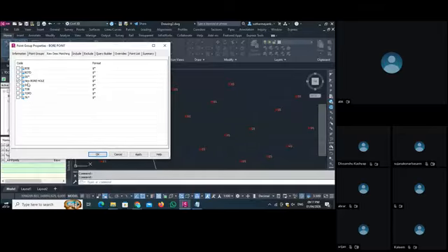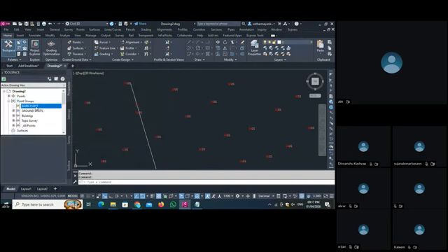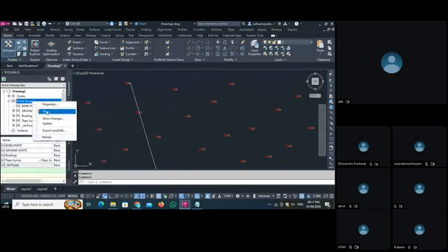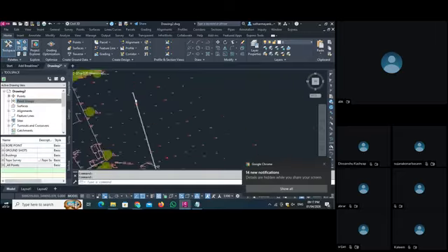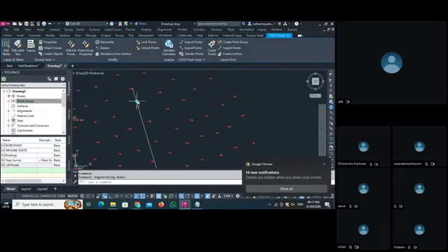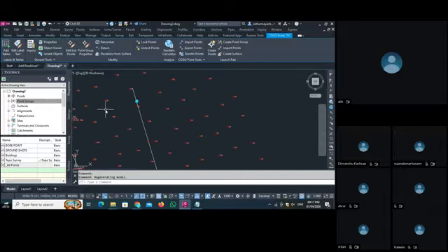So we again want to delete this new one. We have to put the same name as we describe in the description key when we select that manual object, and apply and OK. As you apply this bore point and apply your description key here, all these points are covered in a borehole point group. So this is also one part.